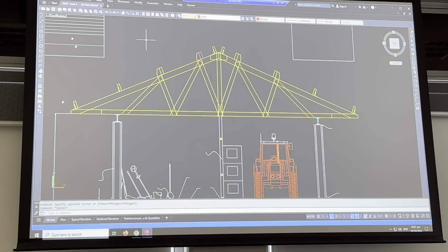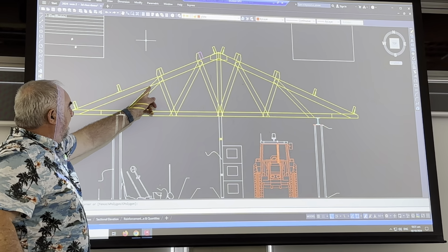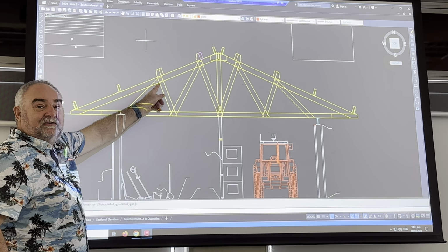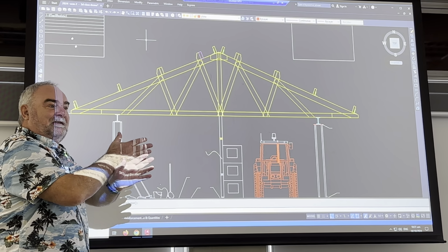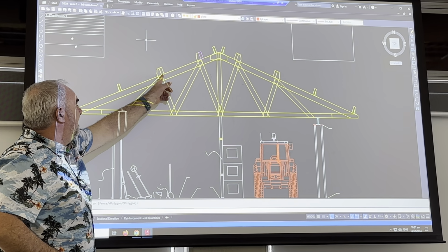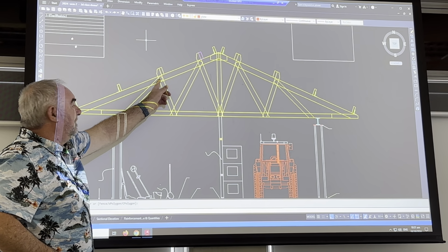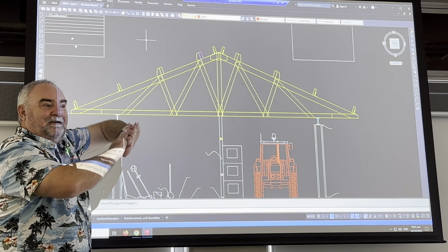So when you do your elevation drawing, I wouldn't suggest you do that for your elevation drawing, because you're going to have to break it. I'll give you an example. When you draw that up in elevation, this line here will be dashed because it's in behind, and that line there might be dashed down here because it's in behind, right?